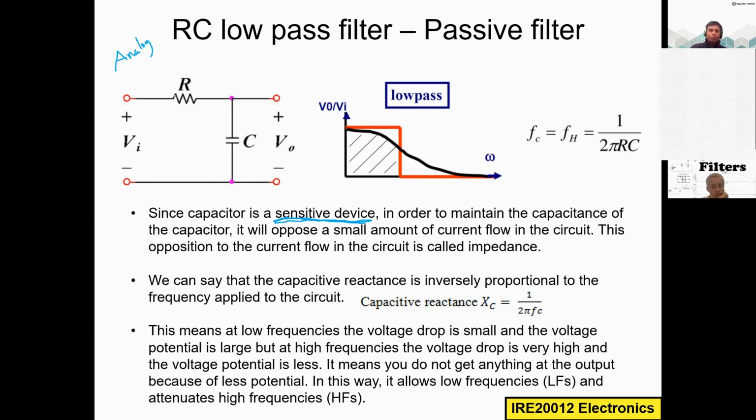Whenever we design circuits, mostly we try to avoid magnetic components and lossy components. What are the magnetic and lossy components? Normally L, the inductor, is a kind of magnetic and lossy component, and also the cost is high and the size is high. Also the resistor, but we cannot really avoid the resistor in circuit design, so we use resistors, but we try to avoid L mostly. But we cannot avoid L in all circuits. For example, in power electronics, L plays an important role.